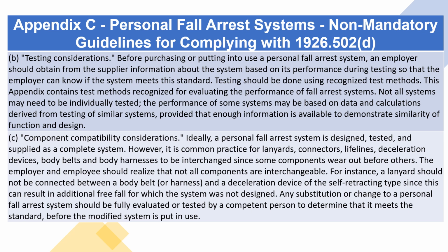For instance, a lanyard should not be connected between a body belt or harness and a deceleration device of the self-retracting type, since this can result in additional free fall for which the system was not designed. Any substitution or change to a personal fall arrest system should be fully evaluated or tested by a competent person to determine that it meets the standard before the modified system is put in use.